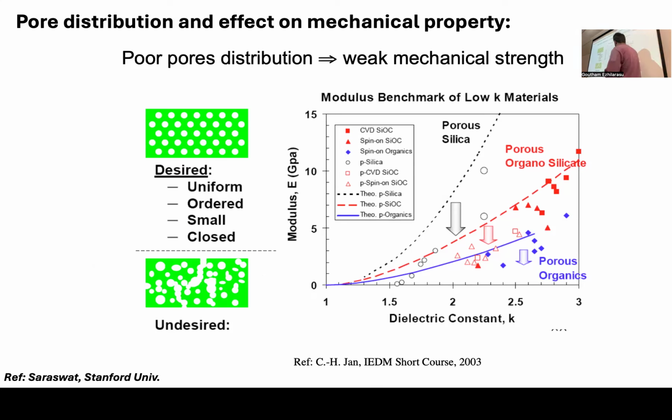And here you see how, for different kinds of porous low-K dielectrics, as you increase the porosity, right, and so you're reducing the dielectric constant, you also have a reduction in the Young's modulus, right, the mechanical property. So as you increase the pores and you lower the dielectric constant, things are also getting weaker, so they tend to also break faster, right? Both in terms of dielectric breakdown, and also in terms of mechanical breakdown and damage.